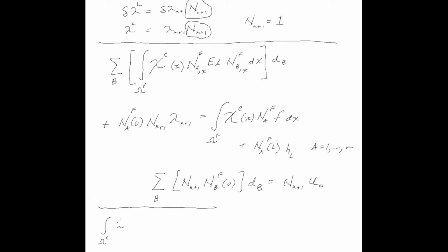I've approximated that integral with an integral over the flex domain, where I have what's called an indicator function, which is equal to 1 if the point is in the CAD domain, or some small value epsilon if it's not in the CAD domain.